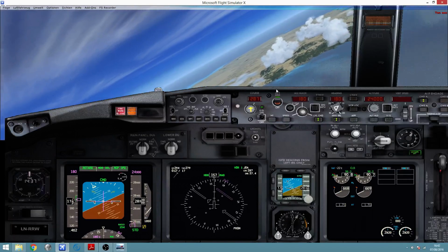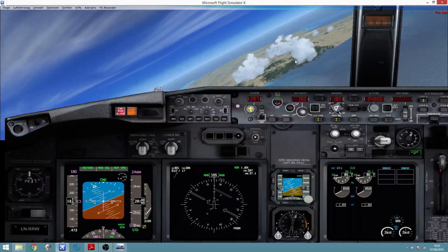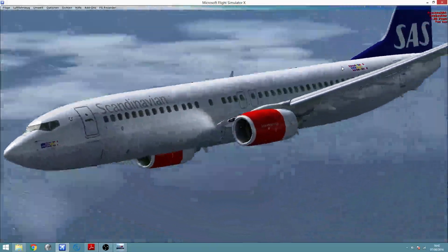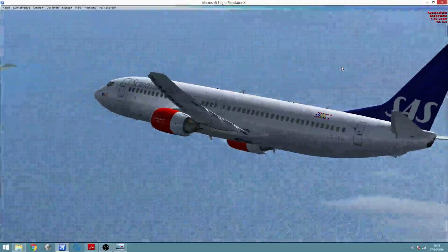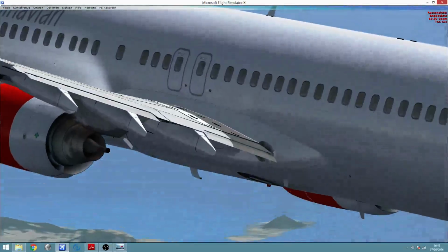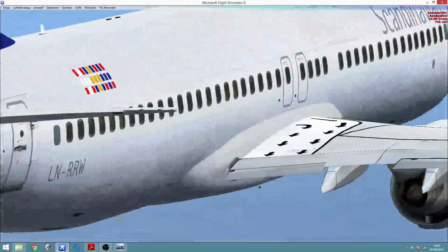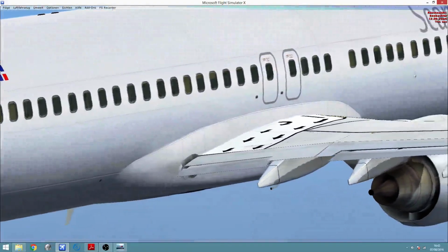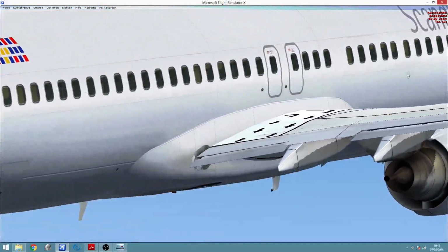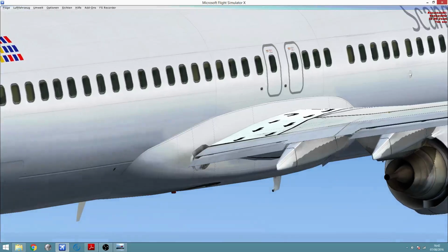Good. And there's something I want to tell you also regarding the flaps. You guys know that aircraft are designed using wing extensions that can help in the provision of lift for landing and for takeoff, and thus increasing the C sub L of the lift equation for the same angle of attack, reducing the speeds at which landing and takeoff can take place.